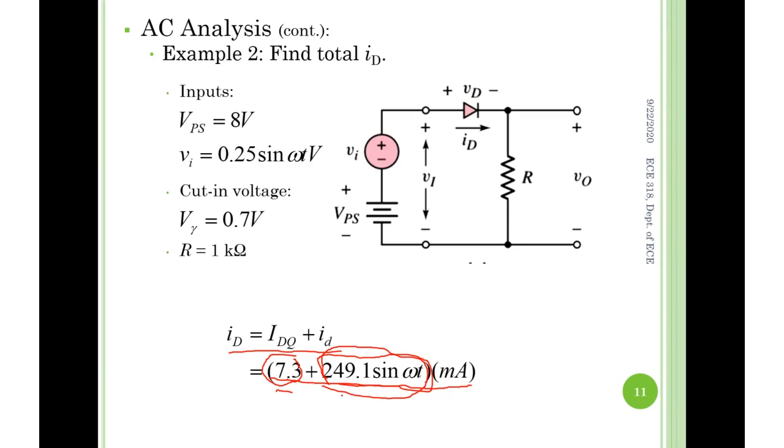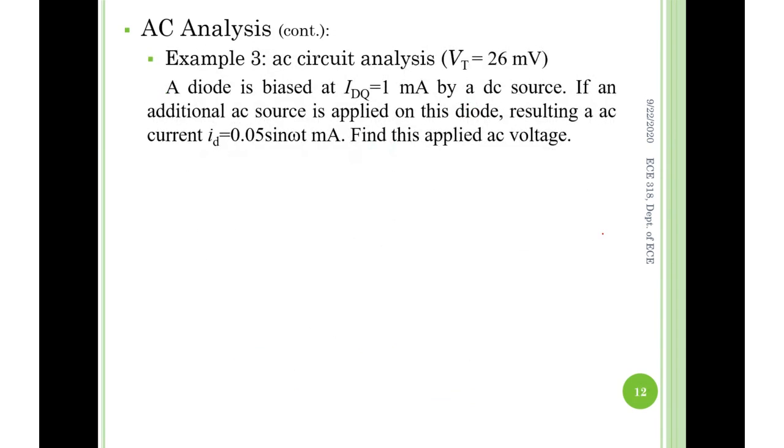conceptually, you cannot, because one is DC and the other is AC. When mixing them together, all you can do is have a plus in the middle. If you mix them together, it becomes one phasor, and that one phasor represents one single AC. You cannot have a DC contained inside anymore. Does it make sense? So when you're expressing a DC plus AC mixed signal, the only thing you can do is have a plus in the middle. You can't do a mathematical combination. So this is example 2, and example 3 is